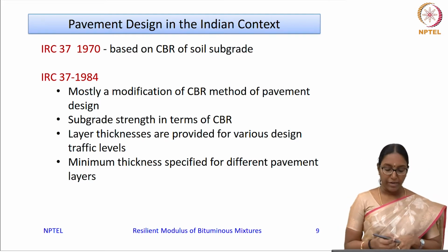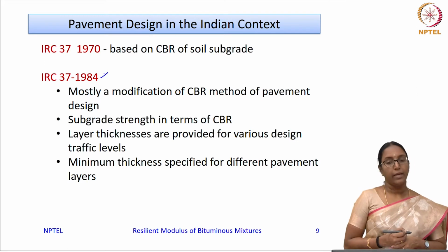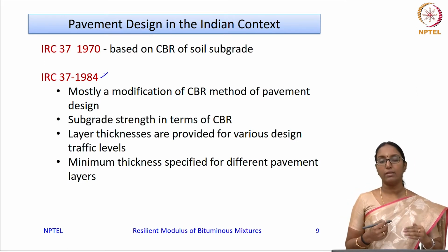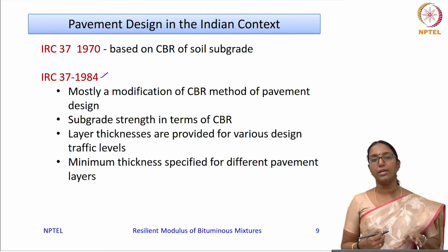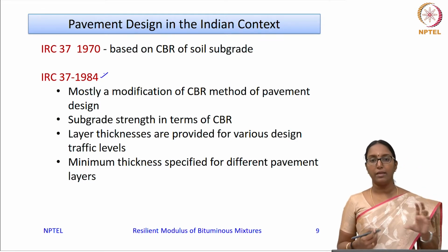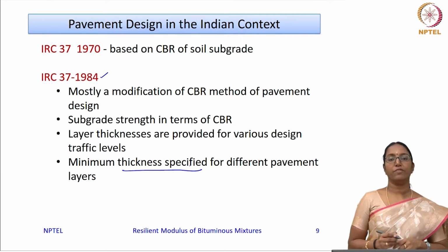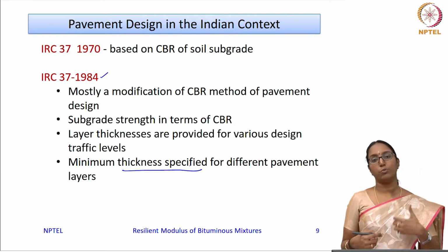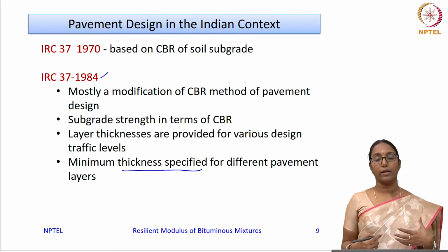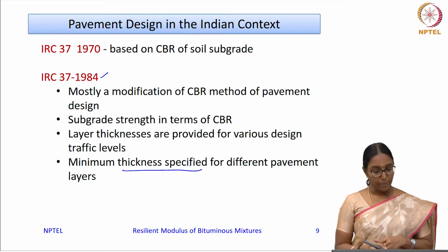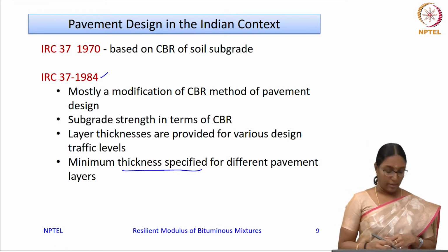It was later modified in 1984. Again, it is an extension of the CBR method itself, where the subgrade strength or CBR forms the basis for finding the layer thicknesses, and minimum thicknesses are also specified for different types of layers. Suppose you are using a bituminous layer or a granular layer, what the minimum thicknesses required should be is also defined in IRC 37 1984.